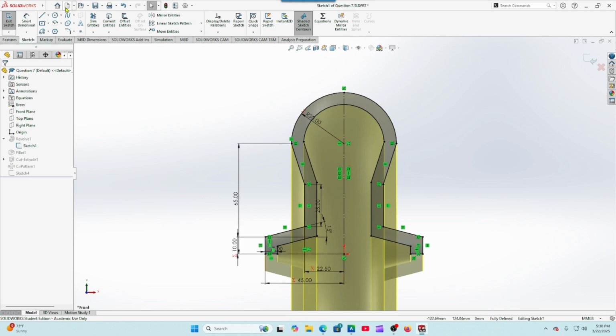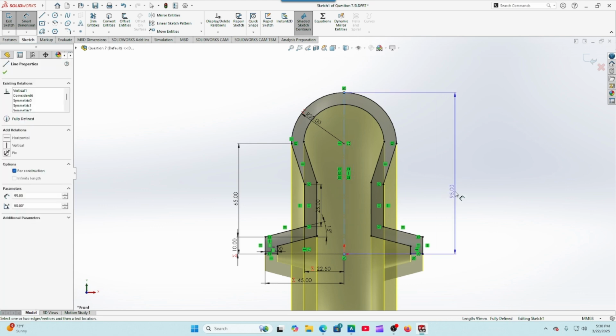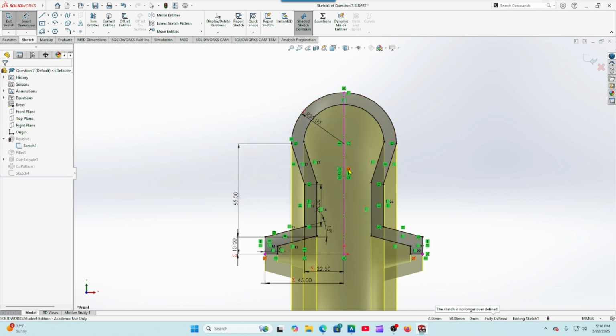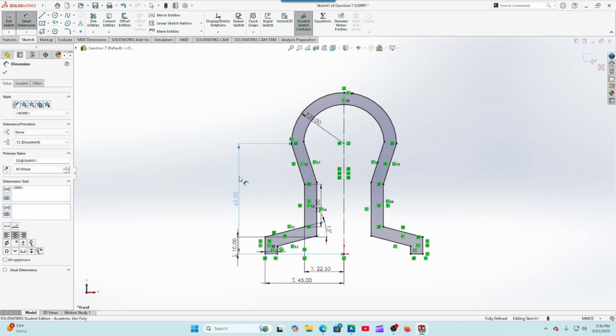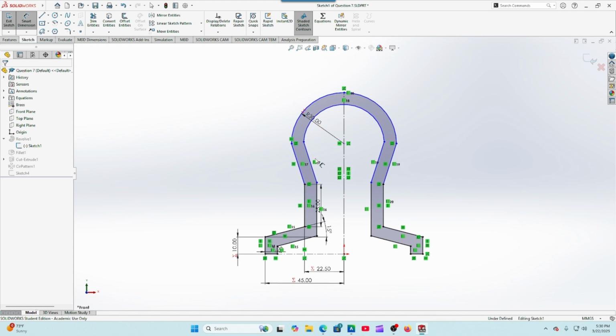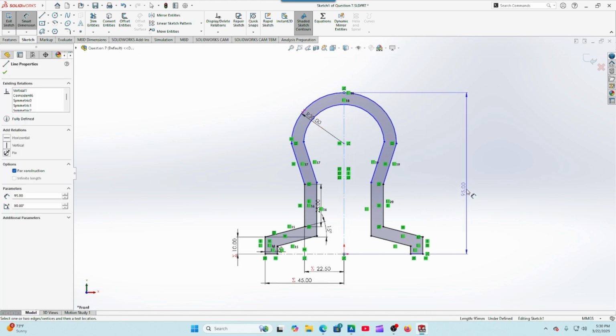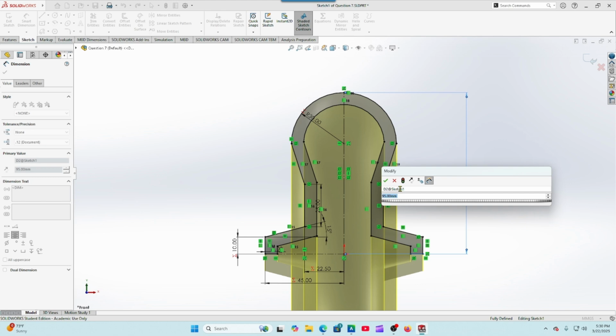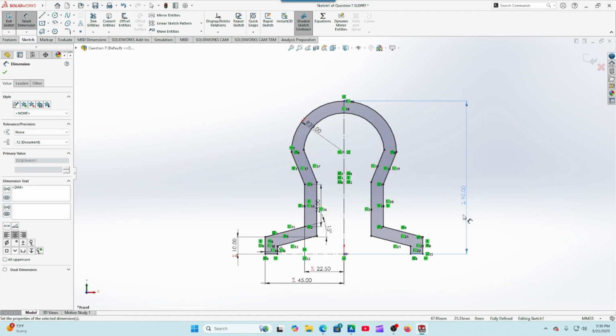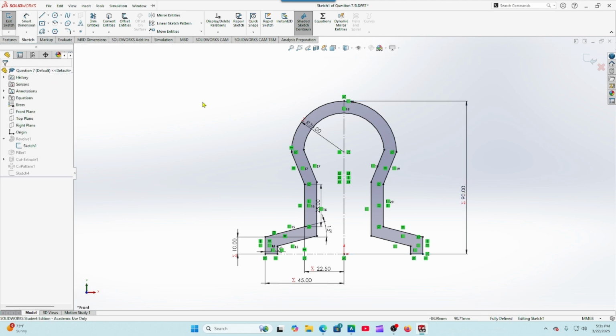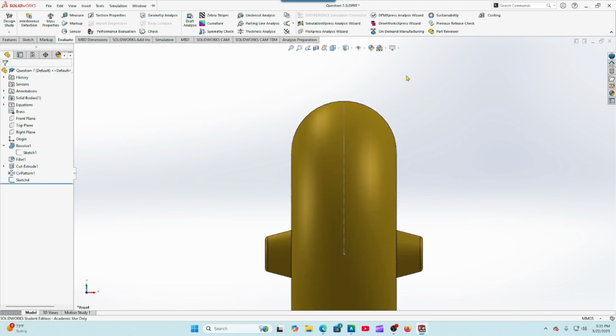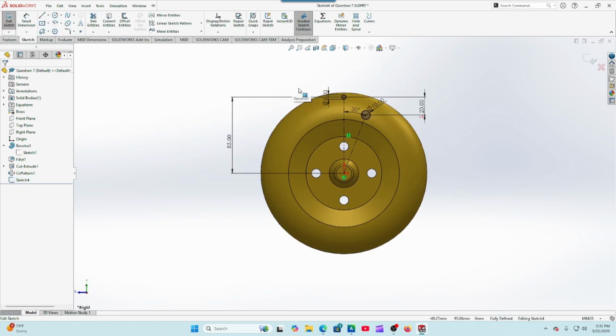Cross there. And let's see something. We have a fully defined sketch, but that should be 90, if I remember correctly. So let's go ahead and take that out. And then we're just going to dimension that, and it's going to be equal to D divided by 2, like so. All right, go ahead and exit out of there. Go back into our original sketch. Now that looks right.